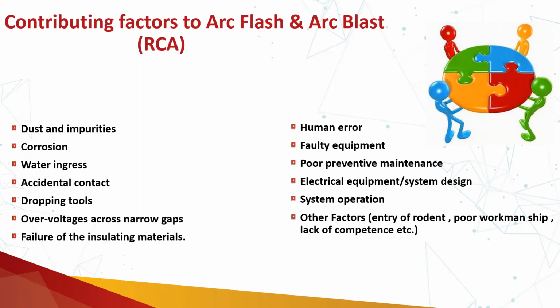If they were not interacting with the equipment, and an arc flash and arc blast event occurred, you won't find the solution in NFPA 70E, because NFPA 70E is about safe work practices. So there was no human error involved, or any bypass of policies and procedures. You are going to find the reason due to NEC non-compliance or NFPA 70B non-compliance.